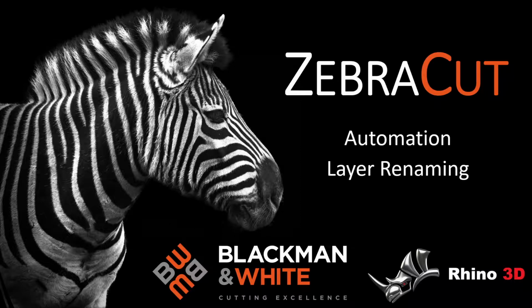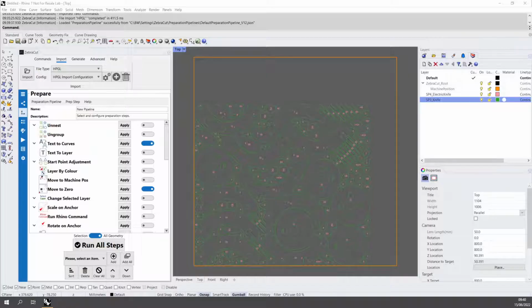In this video we are going to explore layer renaming within ZebraCut. So I have here a HPGL file which I have imported. As you can see, there are two different layers. Now in HPGL there is no such thing as a layer. Rather, you have different tools, different SP or T numbers that are used within the file. And so what ZebraCut very helpfully has done is import the different tools as different layers within Rhino.